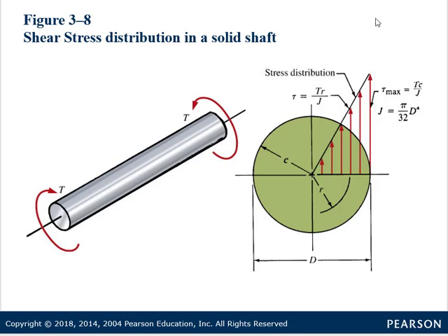These problems are really best off when you work in millimeters, but we're going to talk about that when we do examples. So here is your max equation. Your maximum torsional shear is always going to be at the outer fibers, because shear is at its maximum at the outer fibers of the part.